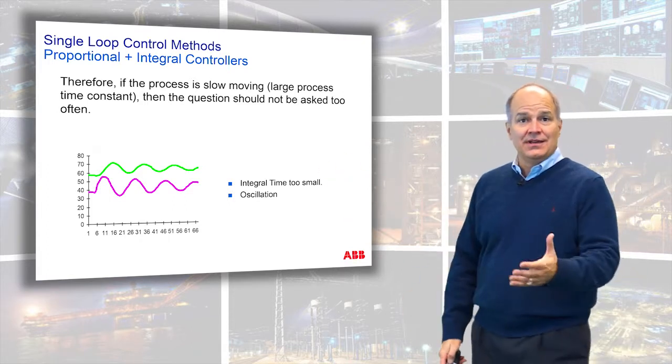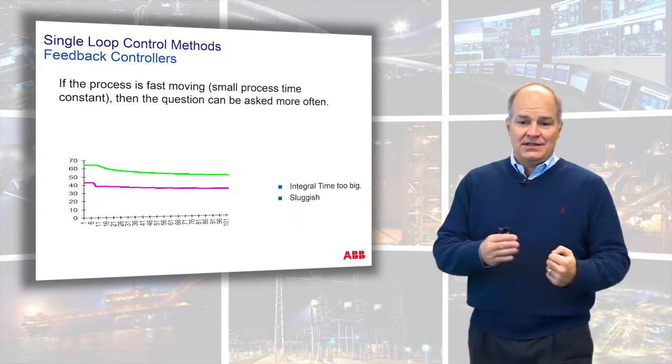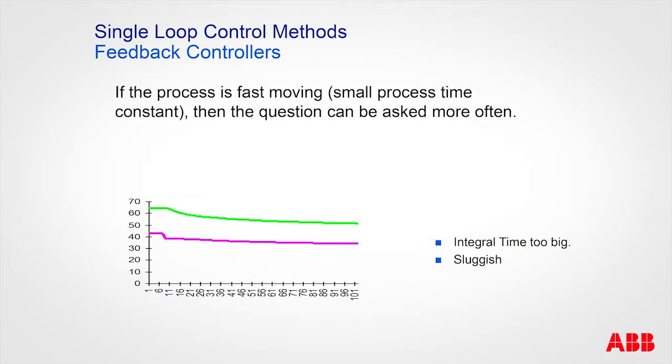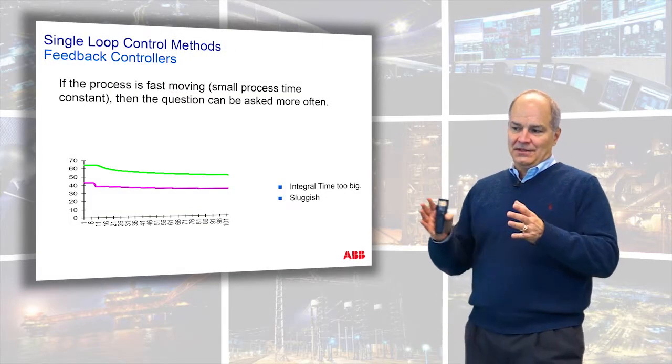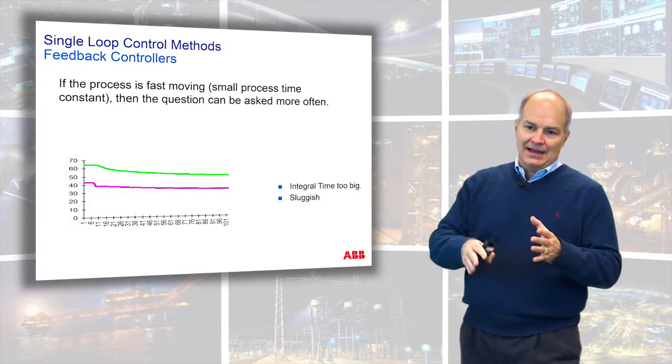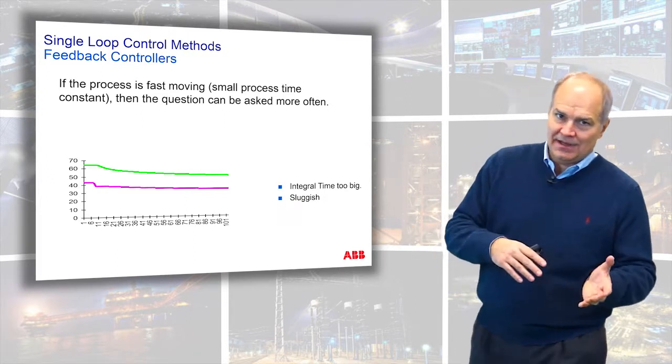And that's what tuning is: how do I adjust this? This is what happens if your reset time is too slow. So the process is like, okay, when are you going to make a change again? So it's just very, very slow. So the question is, if the integral time is big as compared to the dynamics, is that a stabilizing or destabilizing effect?